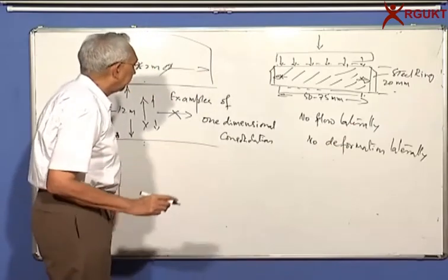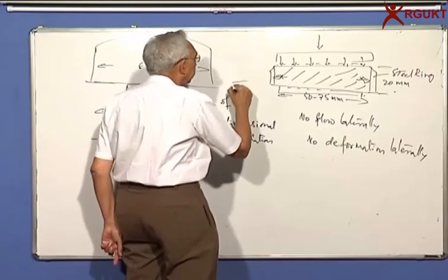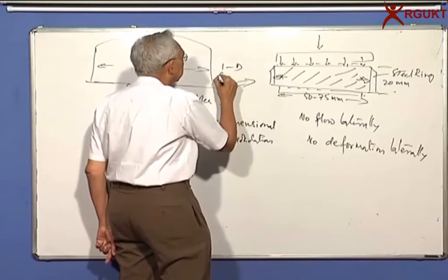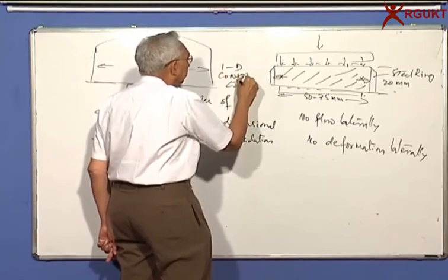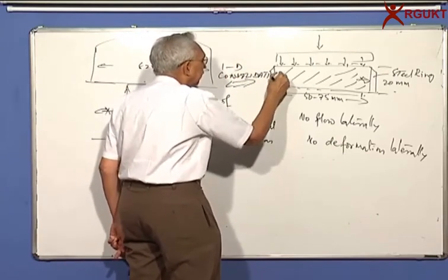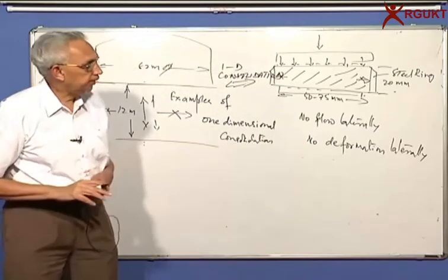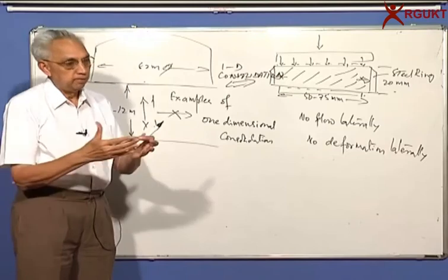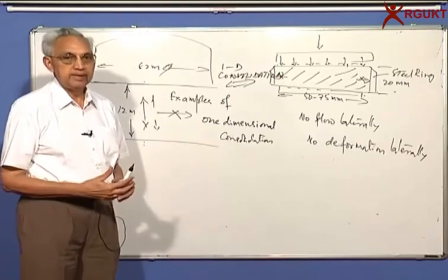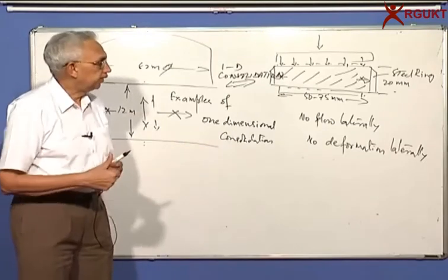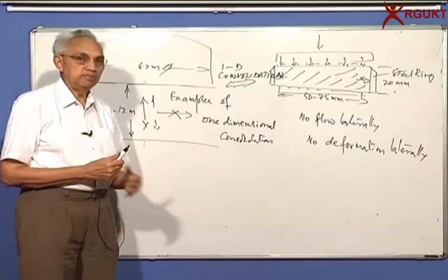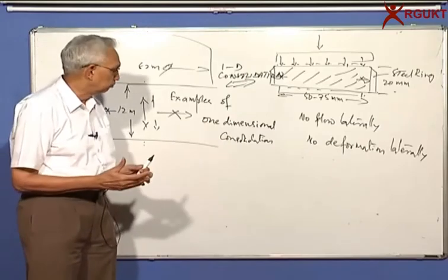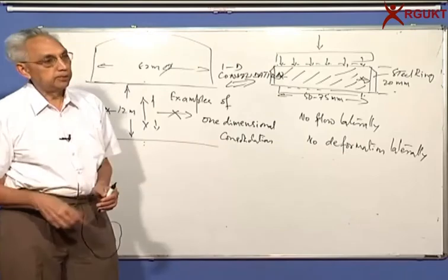So this exactly replicates the one-dimensional consolidation phenomena in the laboratory. And that is how Terzaghi developed this technique, so that we can study what is happening when you have a large loaded area being acted upon by uniform load, and we have a soft clay deposit whose thickness is less than the width of the loaded area.